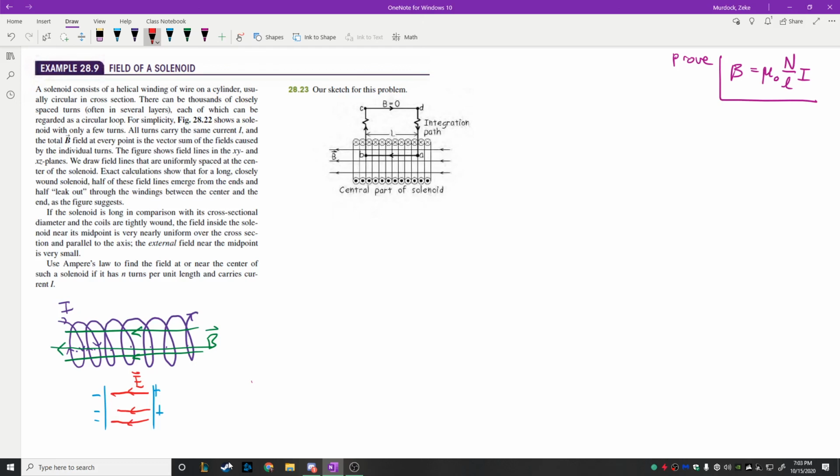And what we'll see is that the solenoid itself, or just the act of coiling up a bunch of wires like this, will actually allow us to store energy inside of a magnetic field in a circuit, and it will form the last of the passive circuit components. We learned about resistors, capacitors. This thing is going to have another name. We're going to call it an inductor. Any coil of wire is going to be called an inductor, and we're going to store energy inside of that, just like we store energy inside of the capacitor.